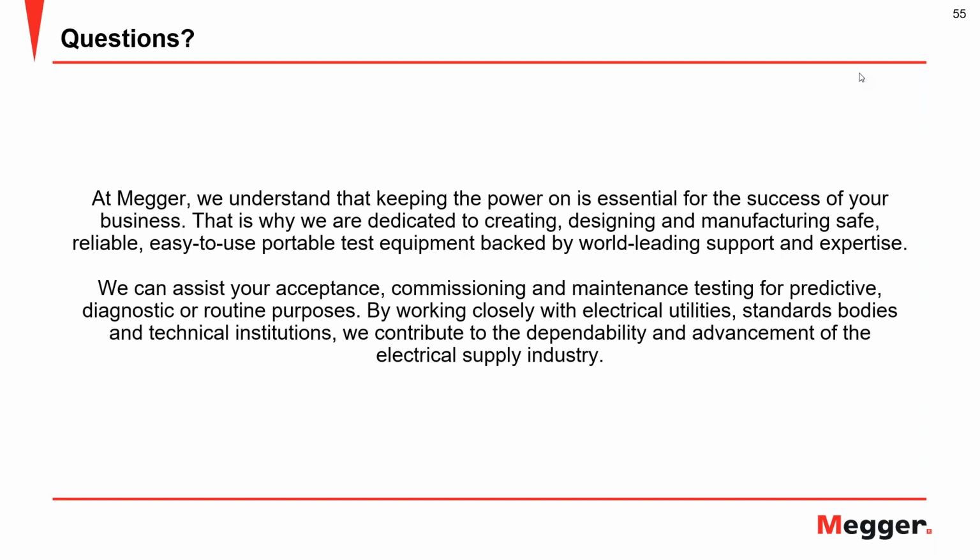But we cannot put a Faraday cage in a field test environment, and that, I think, is very important to understand. I cannot measure something under certain circumstances, like in the factories under a Faraday cage following IEC 60270, and use the results in the field where I don't have the same setup. That is where the problem comes in when people, and to be frank, it's one company that claims this, and there is nothing wrong with the measurement. It's just like Robert was saying, you cannot compare measurements that are not taken under the same test protocol.